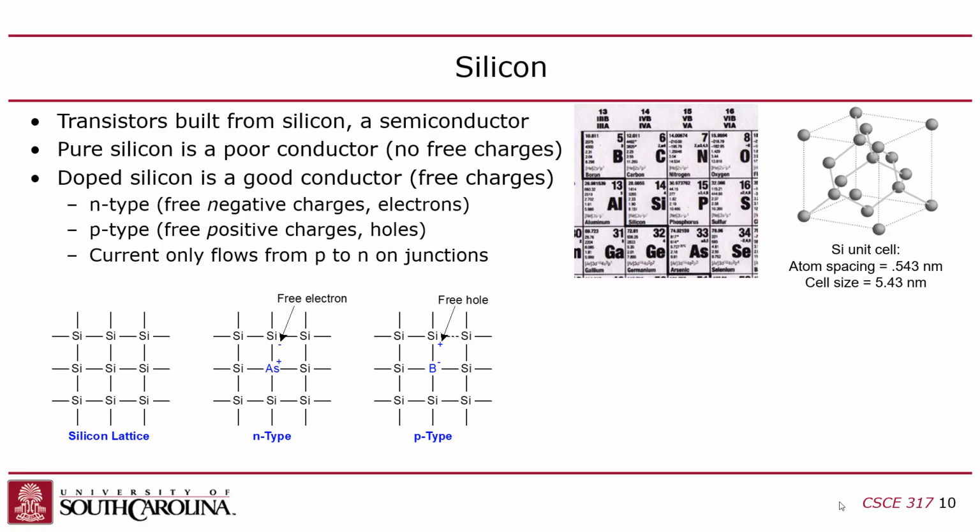So for example, air is not a conductor, but if I hold up 2 pieces of wire and put a very high voltage between them and start putting them closer together, eventually you'll get an arc between the two. What that arc is, is when the air between the 2 electrodes becomes ionized, and the ions in the air become the charge carriers. That's what an electrical arc is. That's really the same thing that happens in the silicon, except instead of an arc, it's these charge carriers that are moving around, right? Does that make sense? So that's basically how that works.